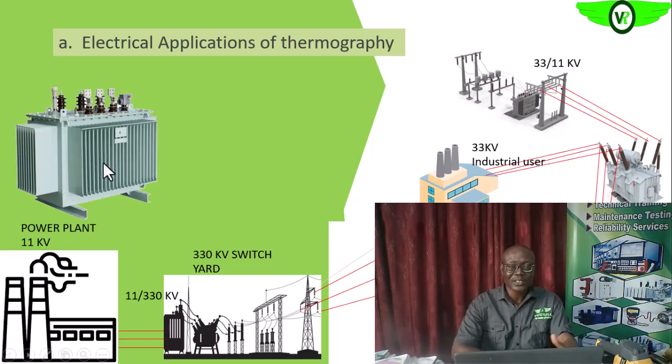Okay, so that oil will absorb the heat from the winding and the hotter oil molecules will move away from that spot where it absorbs the heat. Okay, and then the normal convection will be created. The cooler ones will drop down to the position of the hotter oil, while the hotter oil will move out. So that normal convection will drive the oil into all of these cooling fins, as you are seeing.